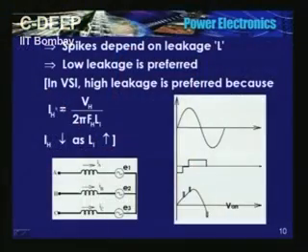See, what is the expression for the harmonic current? Here is the expression. The magnitude of harmonic current of a given frequency is equal to the magnitude of that particular harmonic voltage, divided by the impedance offered to that harmonic. I am neglecting the resistance now.